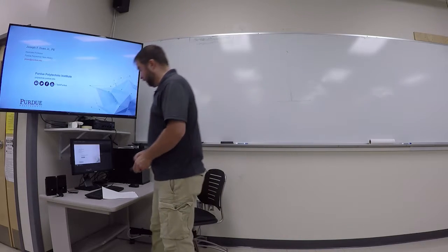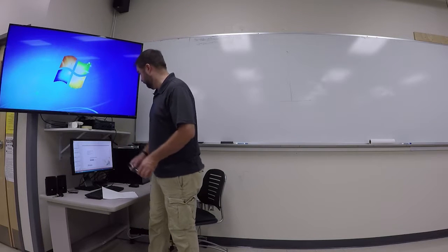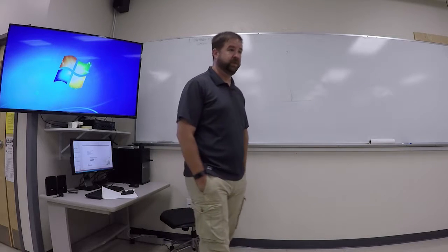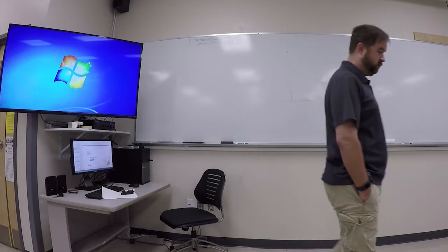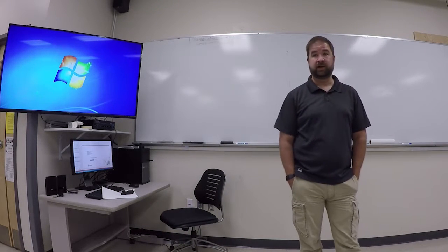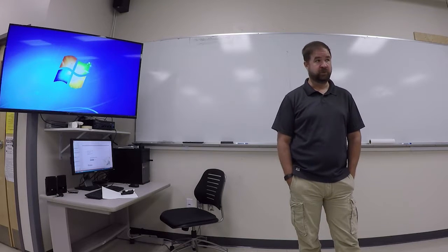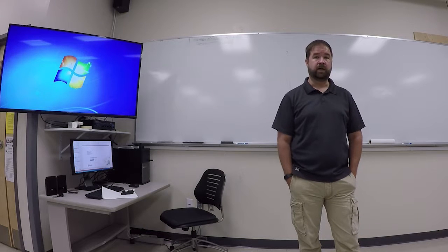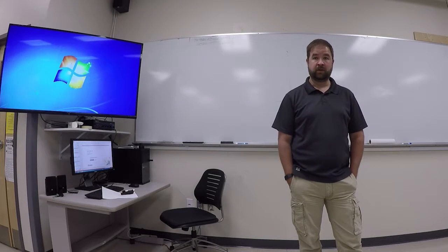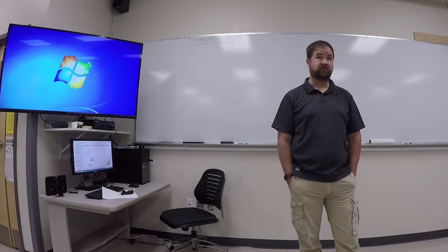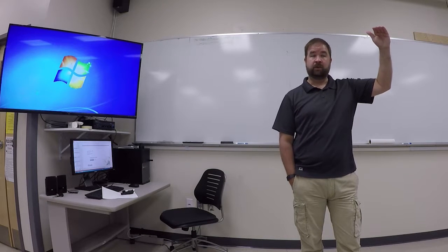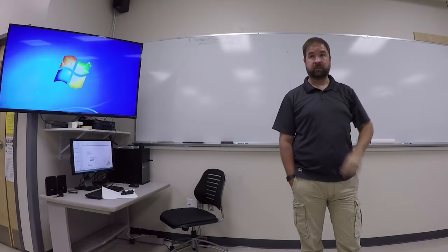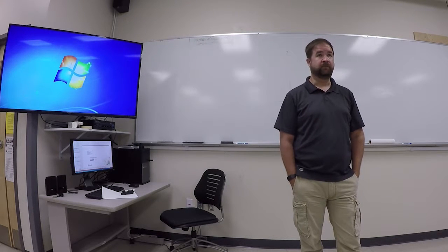Okay, so that's the theory. Talking about SolidWorks, the process for doing an analysis. You want to create the geometry like we have been. So create the geometry like always. Start the analysis package. And when you say new study, instead of choosing static, you want to choose the modal analysis.